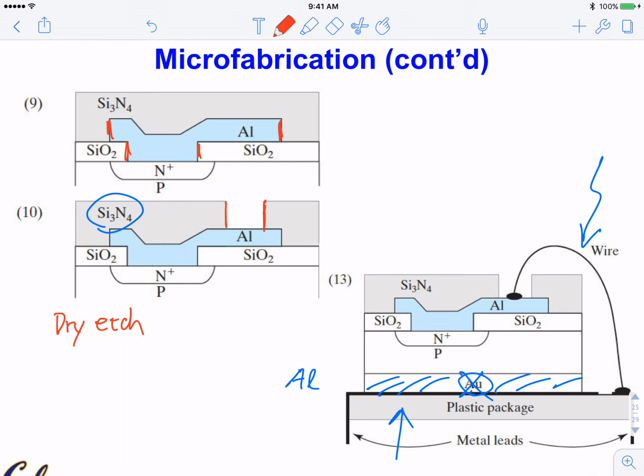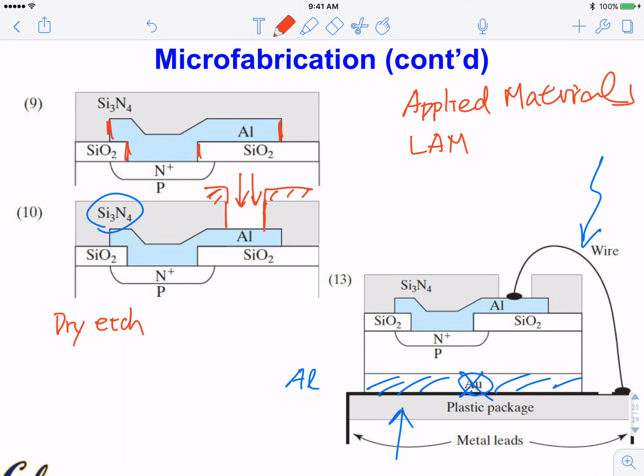And so you energize the ions, different ions for different materials, and then you accelerate them towards your opening. You cover everything by photoresist, so the ions can only attack this area, and you make an opening. So companies around here, like Applied Materials, are a dominant supplier. Actually, both Applied Materials and Lam Research are two dominant suppliers for this type of equipment.